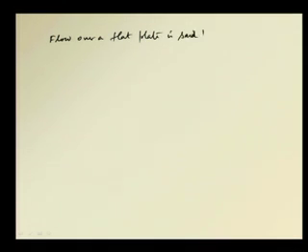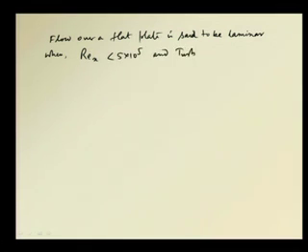Okay. Now, what happens in general is that the flow over a flat plate is said to be laminar, because there can be a lot of issues, I will come to that, when Rex is less than 5 into 10 to the power 5, and turbulent when Rex is greater than 5 into 10 to the power 5.